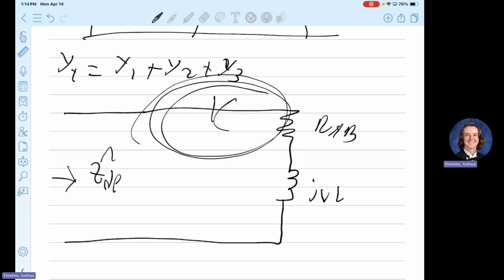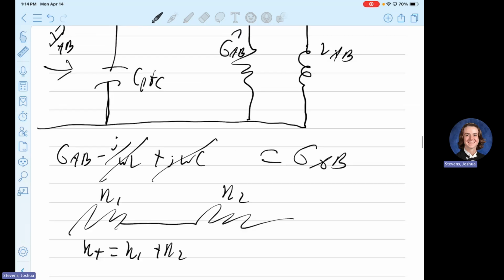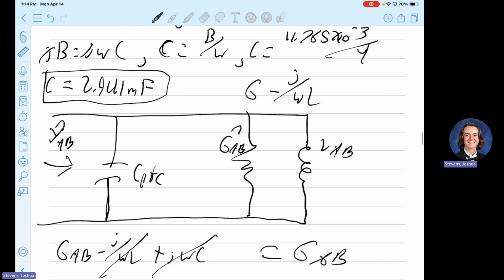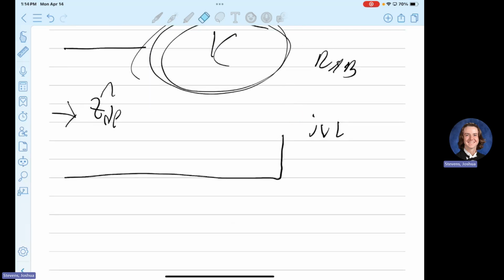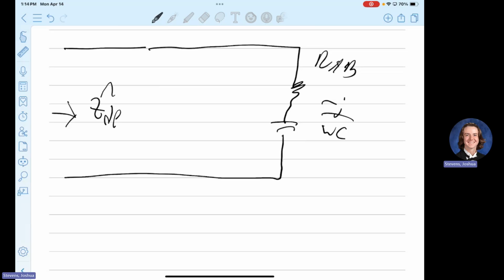The connection part, it's always up in the air. But the previous way of telling you, as in this, since it's a negative susceptance, it's going to be an inductor, and because of that, we have to offset it with the capacitor. And on the flip side, since this would be a capacitor, as in a negative susceptance or negative reactance, sorry, we'd have to offset it with a positive J omega L.